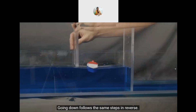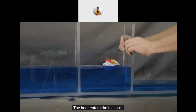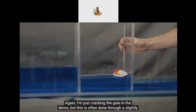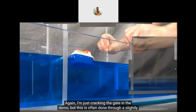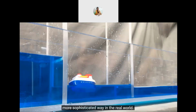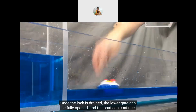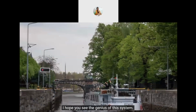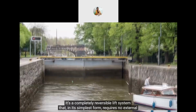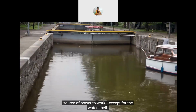Going down follows the same steps in reverse. The boat enters the full lock, the upper gate is closed, and the water in the lock is allowed to drain. Again, I'm just cracking the gate in the demo, but this is often done through a slightly more sophisticated way in the real world. Once the lock is drained, the lower gate can be fully opened, and the boat can continue on. I hope you see the genius of this system. It's a completely reversible lift system that, in its simplest form, requires no external source of power to work, except for the water itself.